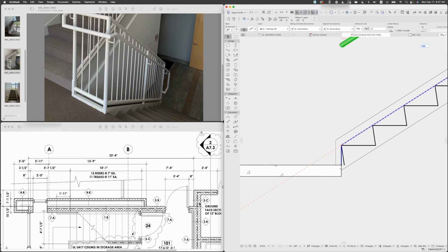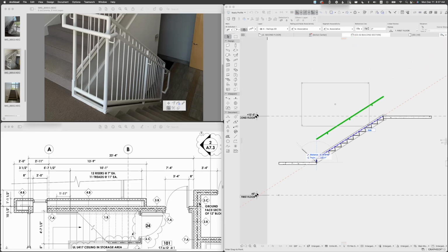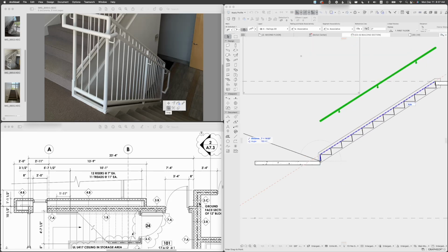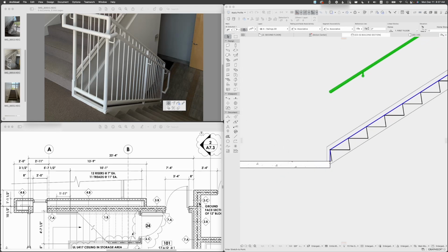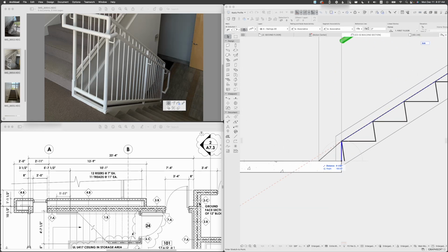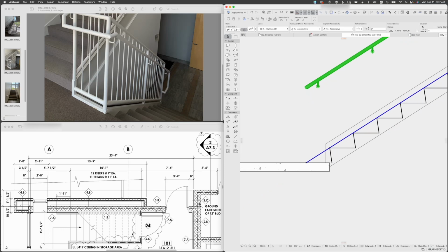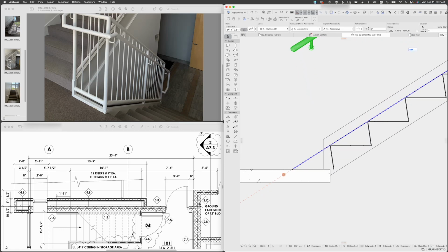We need to move this point right first to here. And I click it. When I click, you see it starts to move the entire thing. It's because by default the last setting was drag, and I want to move node instead. So I would check this option here, and now it let me continue the rail. Snap. This is 11 inches.